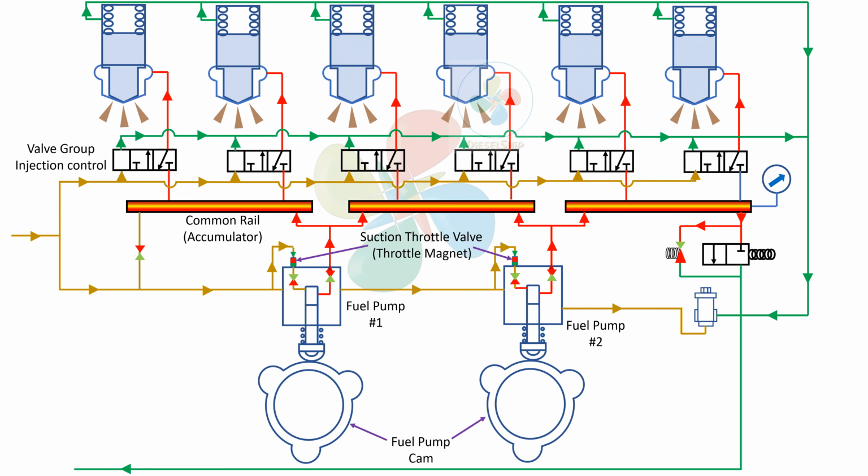There has to be flexibility in injection. Say if you want to alter an injection, right? We have VIT, we have FQS, all these things in a mechanical injection system. But mechanical injection, to do anything, has to have a mechanical action. Mechanical action comes through linkages, and due to that there is a lot of wear and tear, and there is going to be a lag. There are a lot of other associated issues with mechanical actions, right? Whereas electronic injection is so flexible, and the heart of the injection depends on this valve group. This valve group is a 5 or 6 port valve.